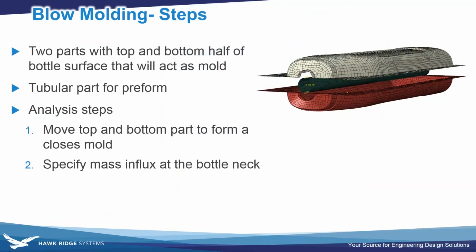Another example of that would be a blow molding simulation. This is really something that probably can't be approached at all in SOLIDWORKS simulation. But if you were trying to simulate something like a plastic bottle or any other object that's molded by shooting pressure in through a thin plastic or polymer sheet, SIMULIA Abaqus can handle the large amount of deformation required to predict that and the complex contact between the plastic sheet and the surrounding die. And it even has the ability to define the right kind of internal pressure loading that would be causing the expansion, causing the actual blow.